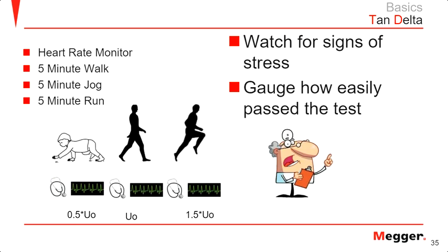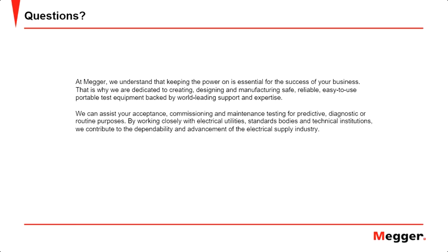You can just see the intensity of partial discharge, but you will never be able to guess where exactly it is coming from. So, can you do that? Yes, but you won't have parameters that you can evaluate to say, hey, this is where I'm getting it from. You'll just see the intensity of partial discharge and that's it.